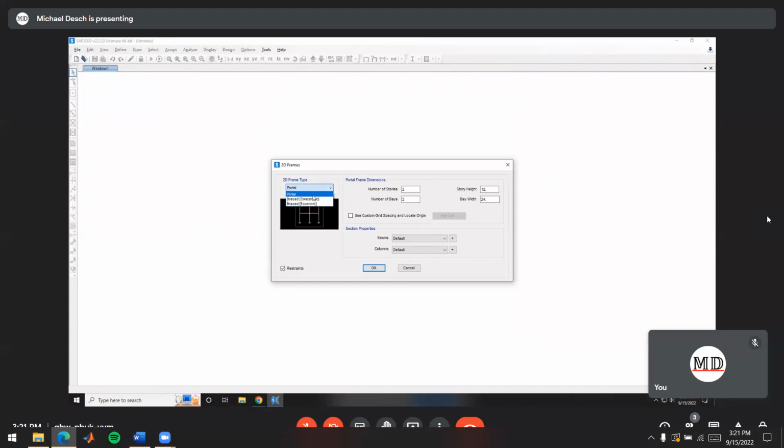In a braced frame, we'll have these kind of diagonal bracing members in some of the bays there, and those will help use axial capacity of those to transfer the loads down to the foundation eventually. There's reasons to use some and reasons to use others. We'll get more into that in the next lab. But for today, we're going to be using a portal frame. It's a real nice typical frame, easy to use and design. So we'll keep that on portal.